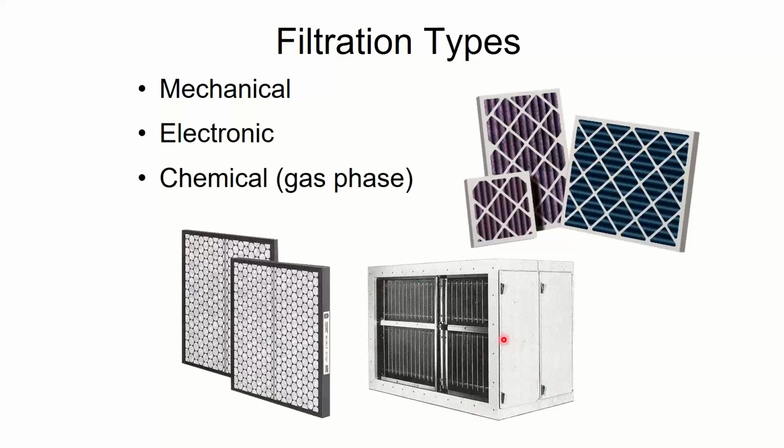And what those guys do is as air is coming through there, they have a grid that charges the air. Let's just say, for example, it charges the particles positive. Then they have these plates over here after that grid that are charged negative. If I charge the particles positive, I got a negative plate. The things cling to the plate, and hence I've caught them.